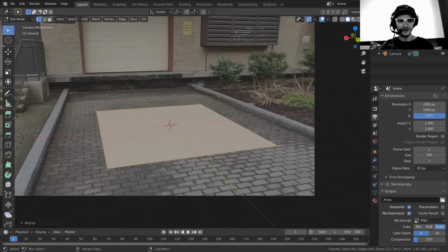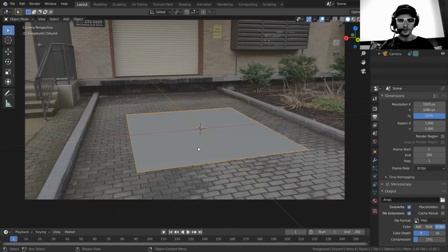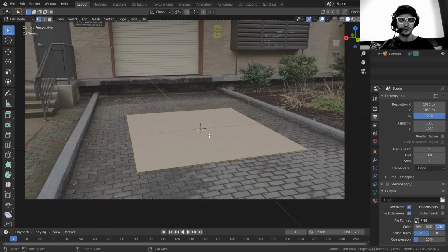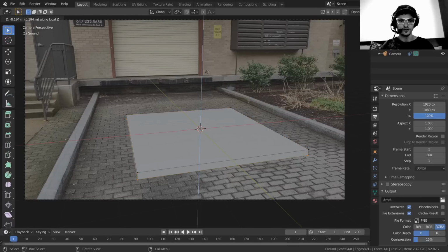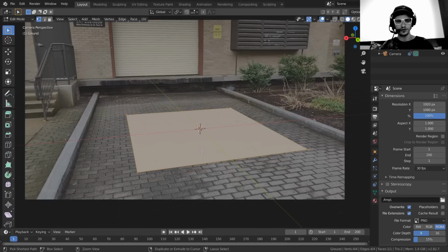Either way, just scale down your plane. Now because we want this to be 3-dimensional, most likely. You don't need it to be 3-dimensional, actually. Maybe we should do a 2D version for this one. Let's do it. So normally what I did before is I just went into edit mode, E for extrude Z, and that just gave a depth, so it's more like a block rotating, but really the principles are the same.